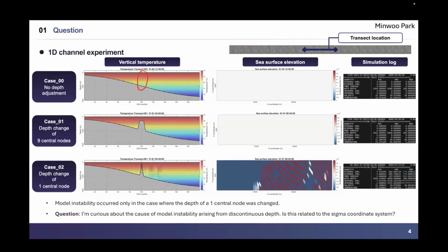But this one is only one single CPU, but your topography is so steep. Your model resolution, your delta T, you cause an error, the error can develop very quickly, but you're so steep. That's not a parallel running issue, okay?